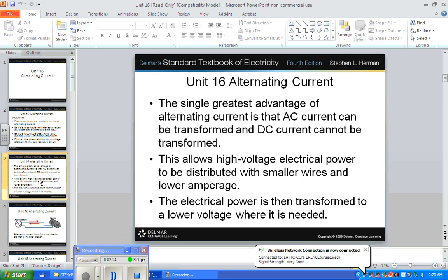Well, if you want to transmit, say, 1,000,000 kilowatts, oh, 1,000,000 kilowatts would be a terawatt, right? That'd be a big one. A gigawatt. Okay, so a couple of gigawatts we want to transform and send here to California. If you send that here at what we would call operating voltage, say 480, 277, you're going to lose most of it over that trip. You're going to probably not arrive with any voltage at all.